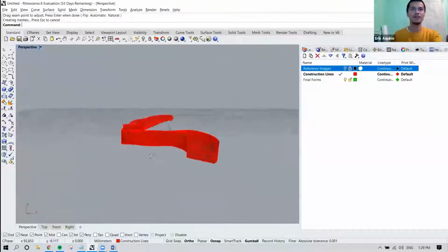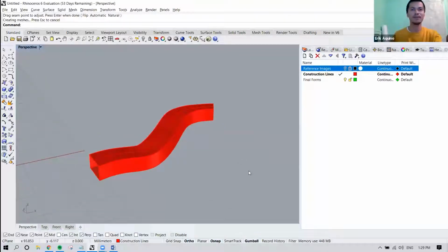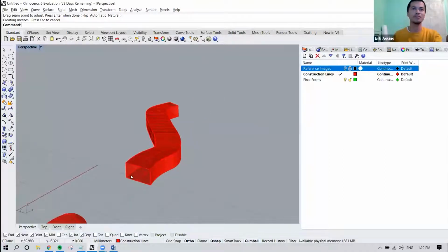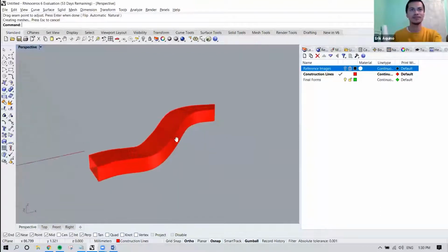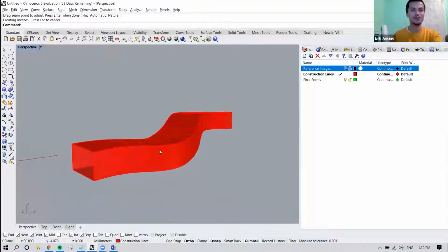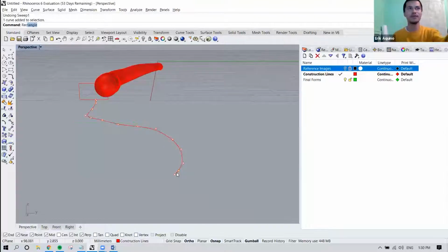And so we have our curve, which doesn't taper, but that's just one way to create an interesting profile that you could sweep along, and that could be useful in some architectural form. And I'll just add another curve here. I'll do rectangle again, and we'll select vertical. So I've typed it into the command prompt, and now we could select our vertical from there. So I'll do a second rectangle that's a bit smaller, and I'll adjust that so it's somewhat in the middle.